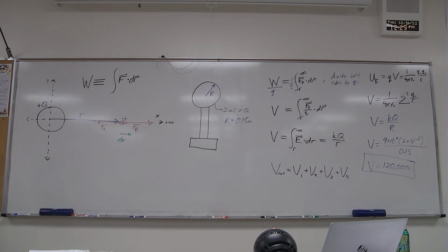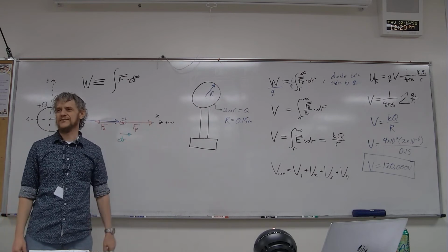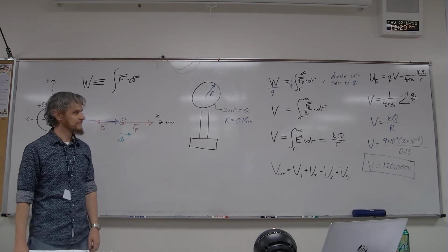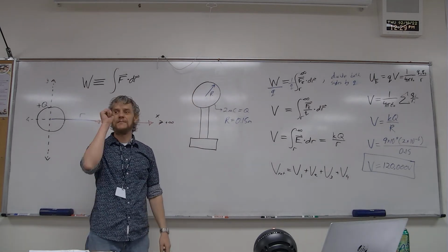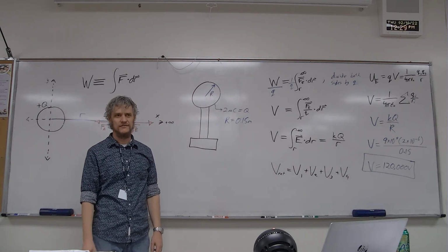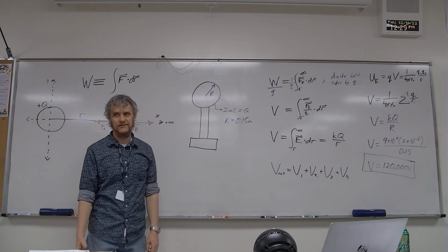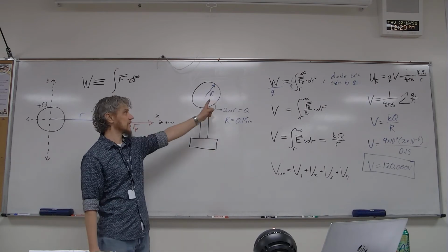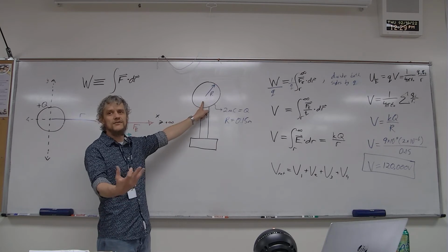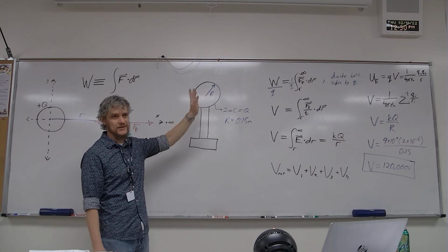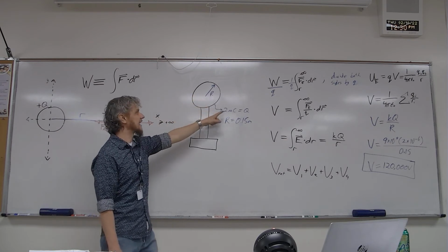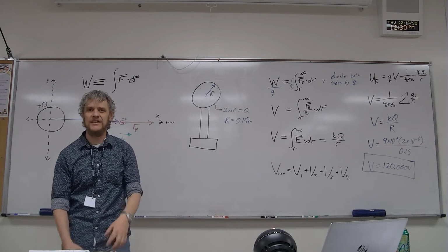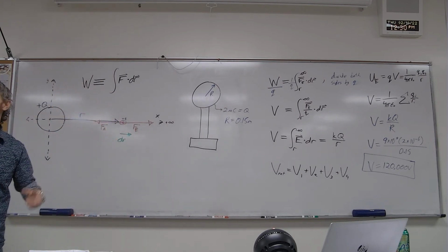But yeah. So why is that? Well, the wall's got a limitless source of charge from the power company, right? Limitless. The sphere here has only a certain capacity to store charge. Hence capacitor, right? We've used that word before. This is a capacitor. If you can store charge, you're a capacitor. It's just not a good capacitor, as we'll see when we start studying capacitance. This guy can only store about 2 microcoulombs based on its configuration. It's not designed to store a lot of charge. If it was, then it would become dangerous.